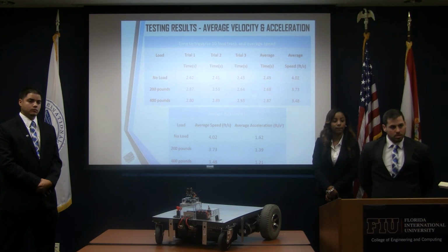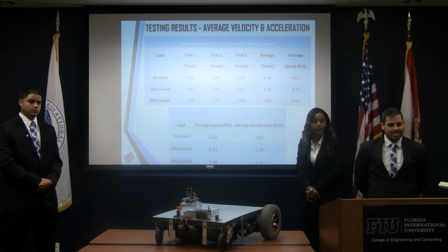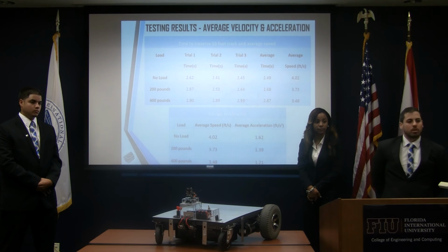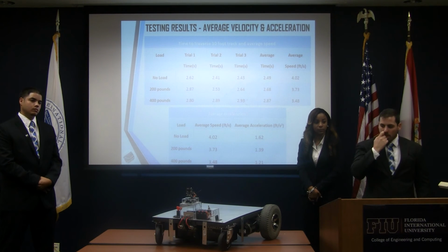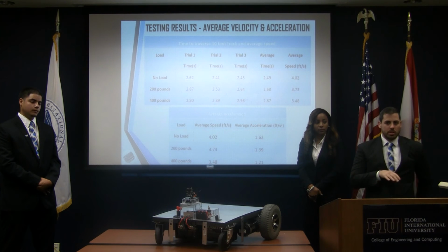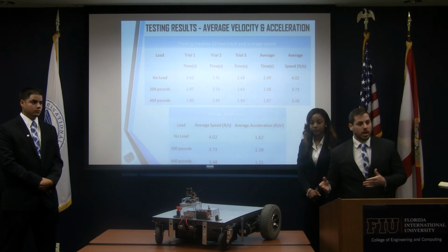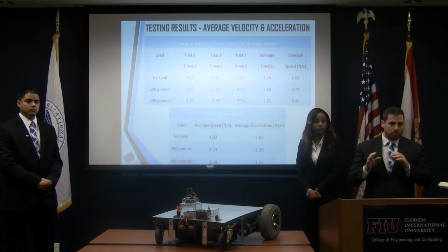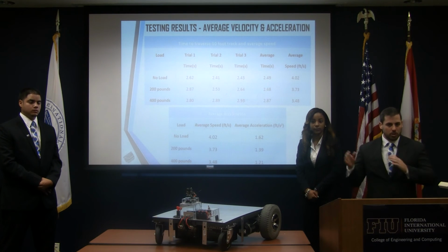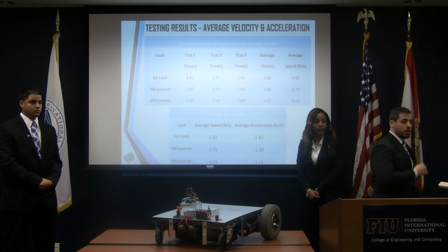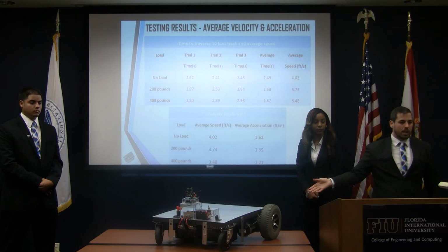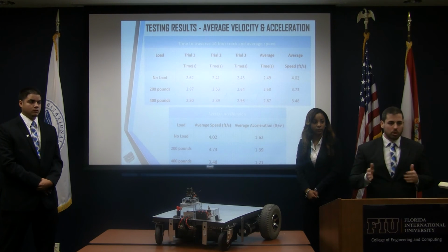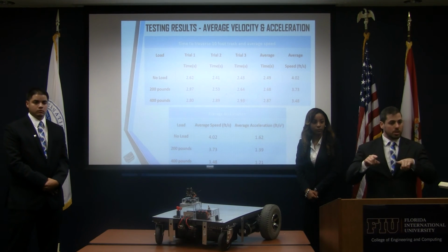Have you thought about incorporating some kind of solar recharging system on this, because you mentioned a warehouse? Or some kind of charging station? We initially thought of taking this outside to test it, and one of the biggest limitations is the camera itself. It's very receptive to different lighting. If you have a target, say a red shirt, and it picks up the red shirt, when you get a shadow on it, it changes the image to the camera, and it makes it very difficult to operate. So outside right now, it can't operate. It can work a little bit, but it basically works off of the size of the target it's detecting.